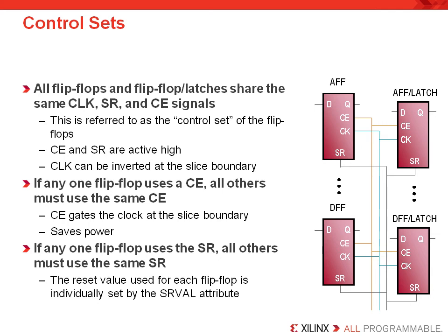Also, if any one flip-flop uses the set reset signal, then all the others must use the same set reset, just like with the clock enable. Now, this is not a real cost to the consumer.